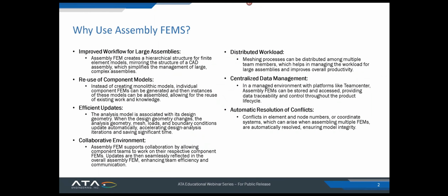And that just means you're going to be able to increase your efficiency, and that also means you're potentially going to be able to manage the organization of the model as well by having people maybe work in their individual folders for those individual sub-assemblies or FEMs. Centralized data management. You can take advantage of platforms like Teamcenter to store your assembly FEMs, and that's just really going to be great for that data traceability and control. And dealing with those node and element ID conflicts, like I talked about, with using the assembly label manager.